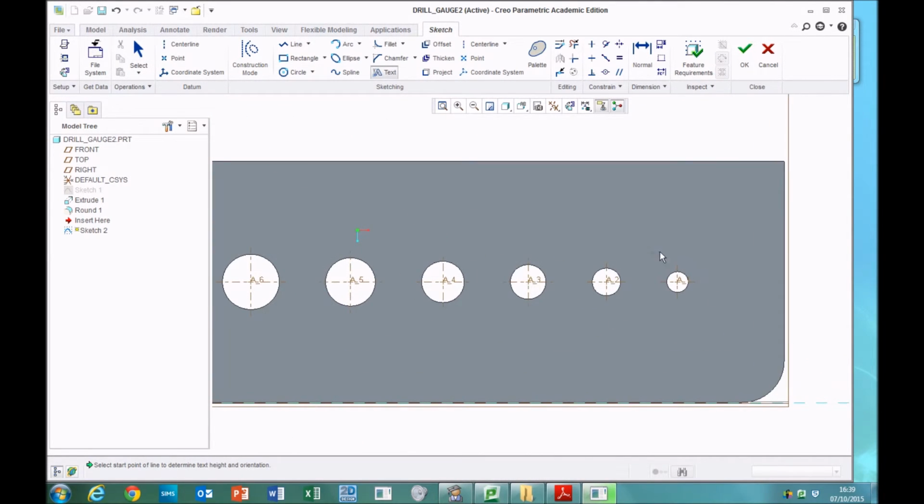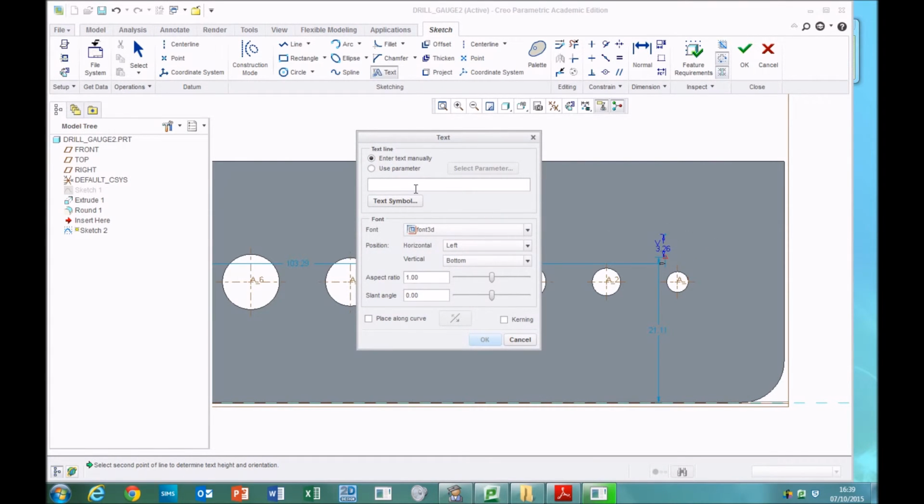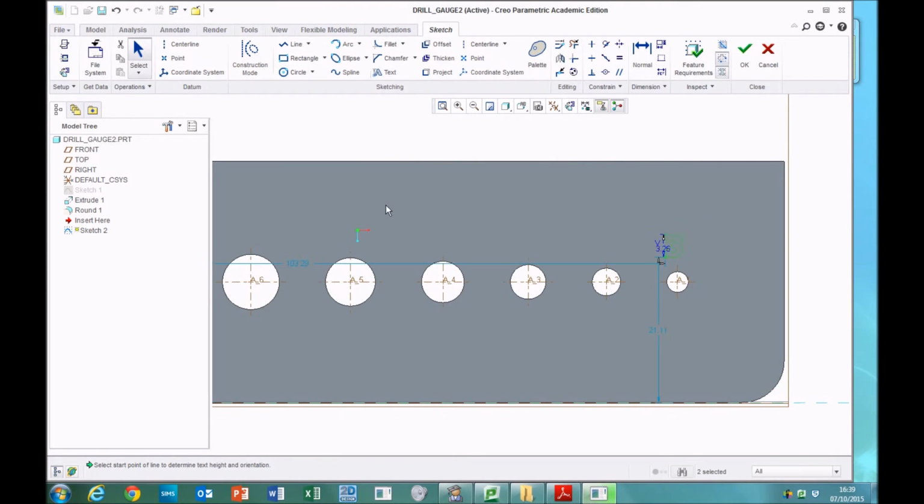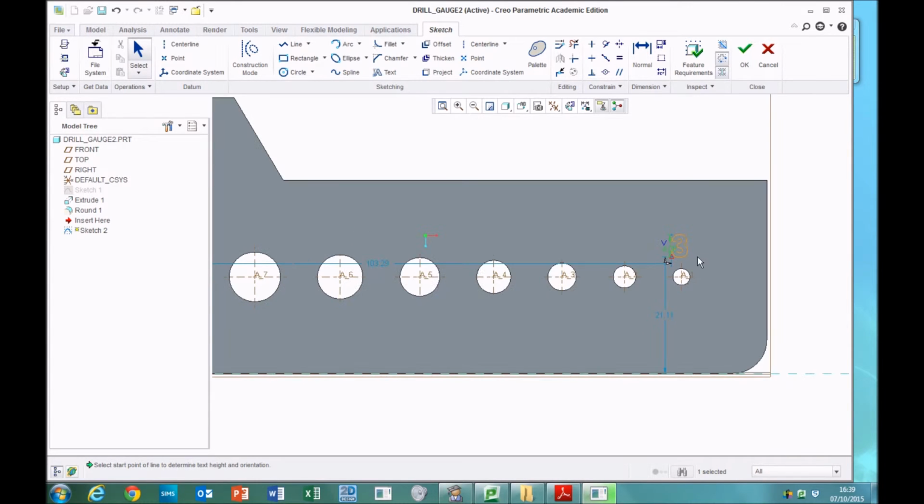And the first thing it asks you to do is to draw the height. So you click the bottom and click the top, type in your number. We're doing a 3mm hole, so type in 3, and then you can find yourself a suitable font. And if you want, again, you can use select to just check that the sizes of that are okay. Make that 4mm tall, set it 22mm from the bottom, and 104mm from the end. Okay, so that's locked in place.